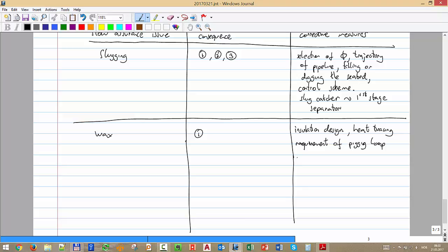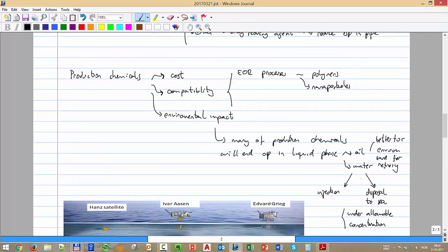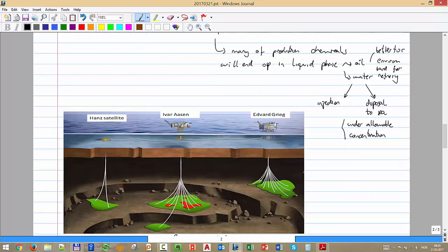Okay, and also chemical inhibitor. And chemical inhibitor takes two things: the amounts to inject and also the distribution system. We have to take those chemicals down to the place where you need them. If you see it is going to happen in that pipe that we put before, we have to put a line from where I have the chemicals all the way to the well. And we will go back to it now at the end of the class.